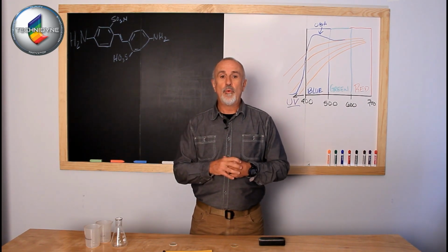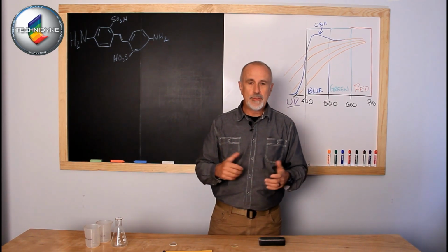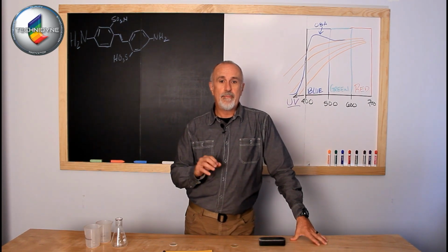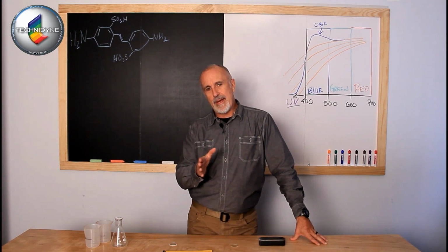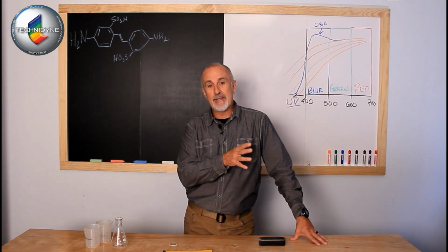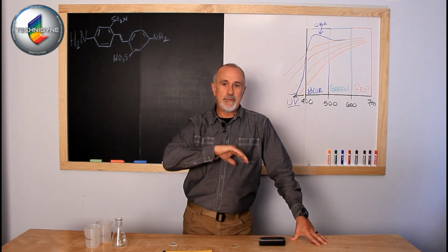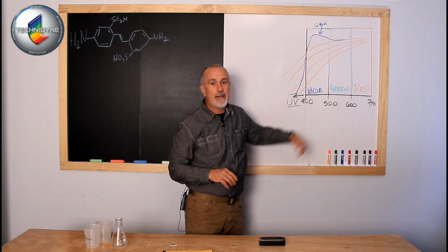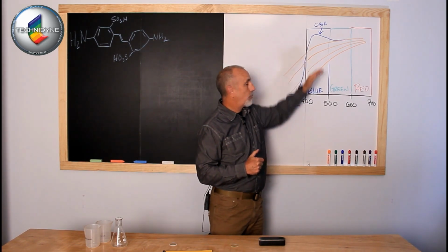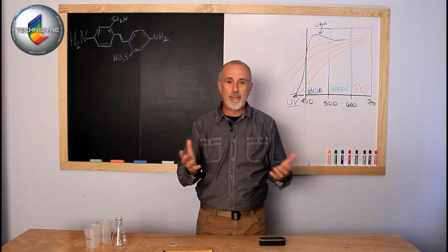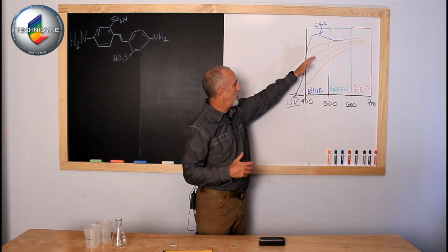It's important we understand what tools we have for evaluating that, and that's really where we come in with the brightness measurement as the primary tool that most people will use when they're dosing and measuring the effect of an optical brightener. When we talked about brightness, we talked about its original setup back in the 1930s by the Institute of Paper Chemistry and General Electric at the time, and that unit was set up to evaluate the bleaching process, which we have right here. When ISO developed their brightness method, likewise, it was to monitor the bleaching process, and really we were dealing at the time, for the most part, with naturally occurring colorants that we were removing in this process.